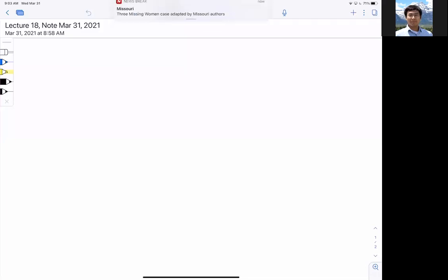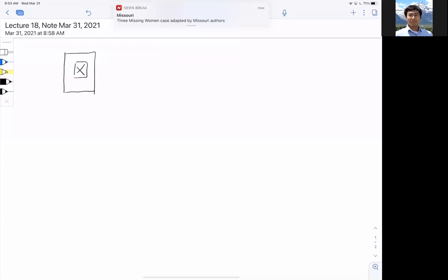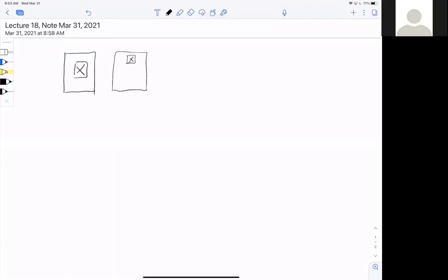For example, if I can draw here, and hopefully you can see my screen, it would be something like this, like an opening duct like that, or something like this, and you have a little bit higher opening duct, right? Now, the difference you probably are very aware of is that for the higher duct, the compression zone might cover the duct. For the lower duct, you have to check whether the compression zone is entirely covering the duct or not. Okay. Now, this is for the irregular section in the exam.